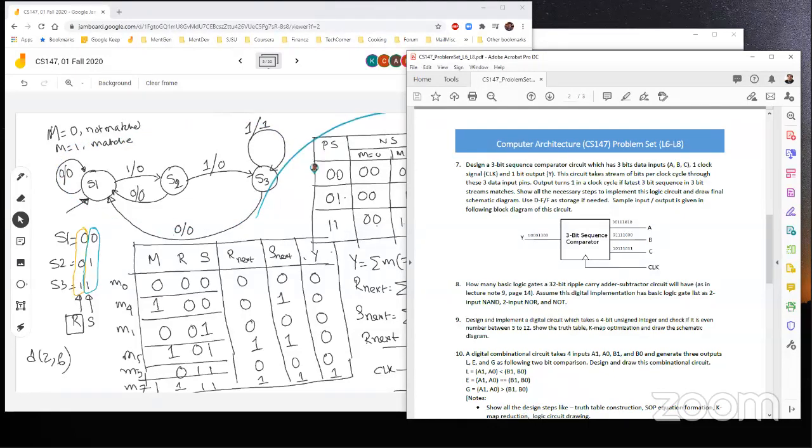From that point, make a state assignment with a number of bits, and replace the state table literal names with the state assignment values, and then go to the truth table. These are the challenging parts. Once you have the truth table, you determine the logic equations, and there you go. You can use the K-map and everything to make the circuit work.